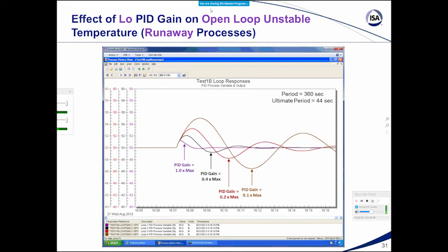It's very high gain. And the offset, probably not realized, the offset from set point, if you don't have any integral action, is inversely proportional to controller gain. So if you have a very high gain, you have a very tiny offset from set point, and you really don't need integral action. And that's the principle, actually, of a good valve position controller.